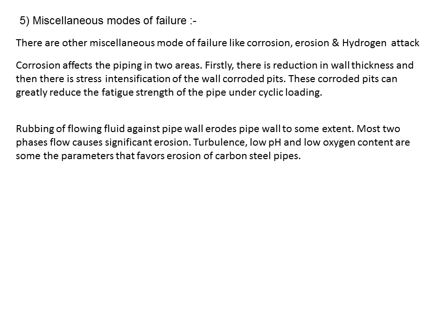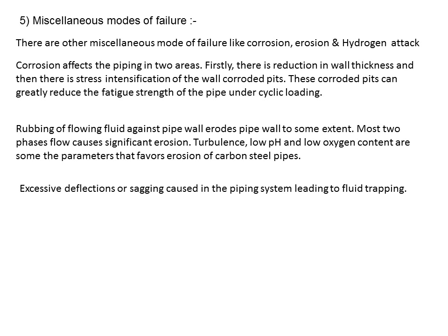And then we have excessive deflection or sagging, which is caused in the piping system, leading to fluid trapping, and generally in condensate systems this becomes a serious concern.